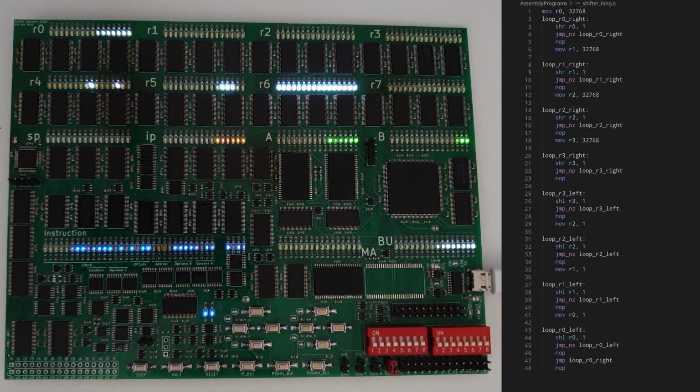You might be thinking that I'm just typing on the computer right now, but that's not what's happening. Every single keystroke is actually sent to the computer over the serial port, which then echoes it back, and this echo is what's being shown. If I, for example, count up, then R0 will count up too, because numbers in ASCII are just the actual number OR'd together with hex 30.